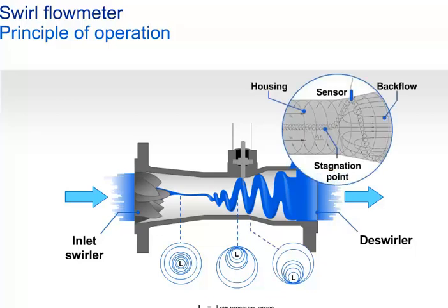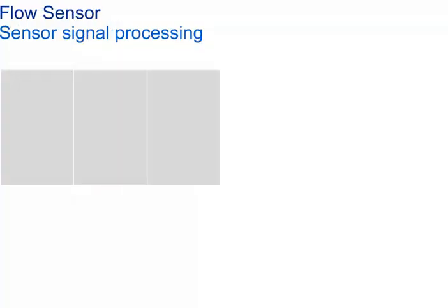The frequency of this secondary rotation is proportional to the flow rate and is linear over a wide flow range for optimized internal geometries. This frequency is detected by the same piezo sensor ABB uses for the vortex flow meter. In addition to the shape of the inner geometry, the piezo sensor also plays an important role in the swirl primary signal.